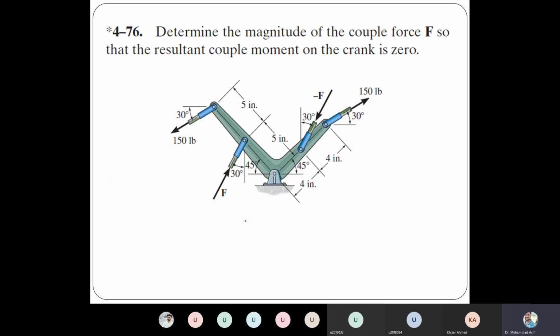Yes, sir. Right. So this is a similar one. Please try to practice this one, because it is a similar problem with a very simplified form of the forces. What you need to do is resolve each force into components. For example, this force can be resolved into one component along the x-axis and one perpendicular to the x-axis. Similarly, for this force, one component along the axis and one perpendicular to that axis. Each force can be resolved into parallel and perpendicular components.